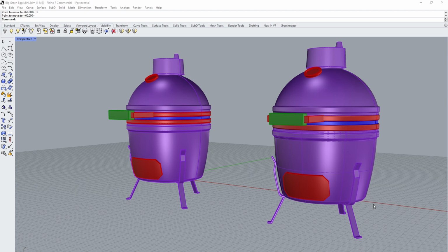The truth is that Revit, when it's not doing things parametrically in the work environment, in the family environment, can just be very, very brittle and difficult to create nuanced geometry with. And for that reason, I've taken to doing a lot of the more complicated non-orthogonal families in Rhino and then bringing them into Revit. And this is not without its challenges, but on balance, it has proved to be an effective workflow for me.